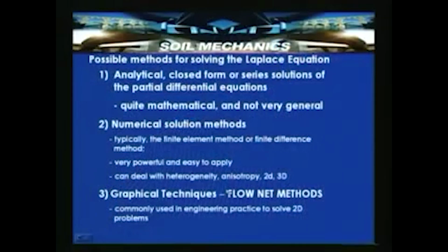They can deal with heterogeneity. But the graphical techniques, which are called flow net methods, are widely used for estimating the flow of water through soils in the case of 2-dimensional structures, commonly used in engineering practice to solve 2-dimensional problems. So, the flow net methods can be applied for computing the flow through a 2-dimensional plane, so that you will be able to compute the seepage or leakages occurring in earth dams.